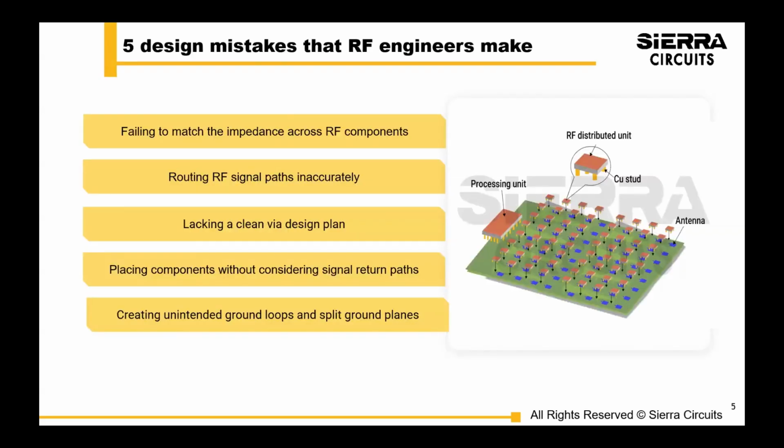So let's start with some high level, common mistakes RF engineers, or basically any engineers getting into RF, can make during their layout phase. Definitely RF is a journey, and there's definitely lots of prototyping that happens. So try and take what you can from this webinar and presentation and our design guides and hopefully improve your journey. So, you want to make sure that, of course, you match impedance across the RF components. If you don't, you can get reflections and signal loss.